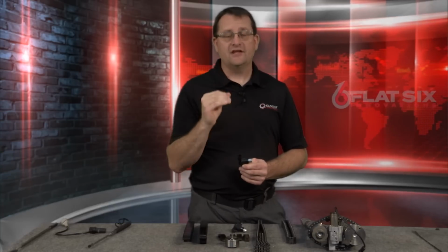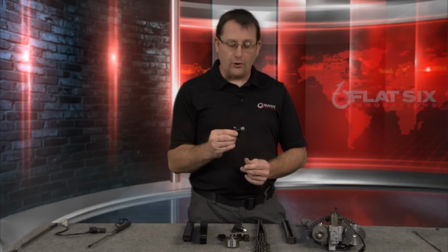You plug it in, you go down and select camshaft deviation 1 and 2, you look at nominal values, and you pay attention to where the camshaft positions are. That's another whole video, okay? But right now I'm trying to tell you, before you go buy this sensor, you need a Durametric anyway. Just go buy it and see what your camshaft deviations are, okay? If they're above 6 degrees, which is the factory allowable for camshaft deviation, then you have a problem. It is out of tolerance.